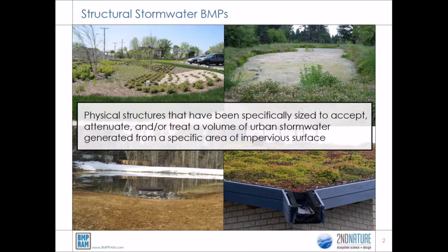In most instances, structural BMP sizing is based on site considerations to treat regional stormwater volumes generated from the contributing urban drainage area, such as the 85th percentile 24-hour precipitation event or 20-year 1-hour storm. Other guidance videos are available in this series that discuss how to correctly identify and distinguish the various types of centralized and decentralized structural BMPs.